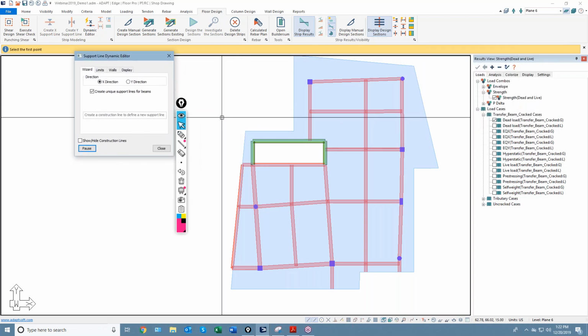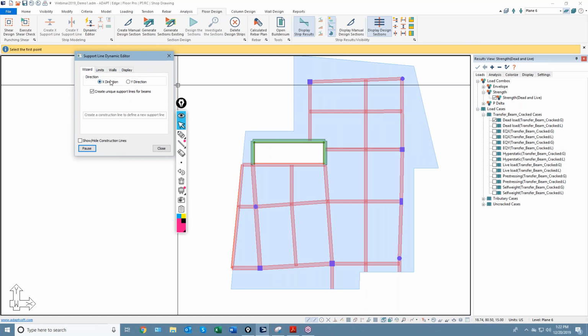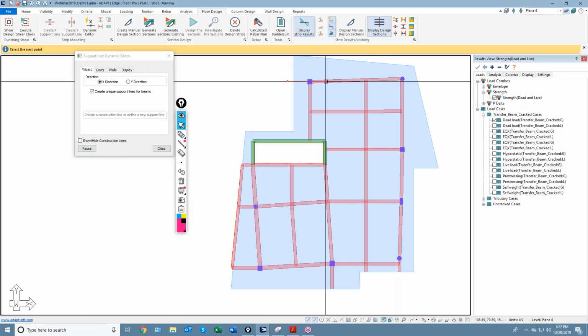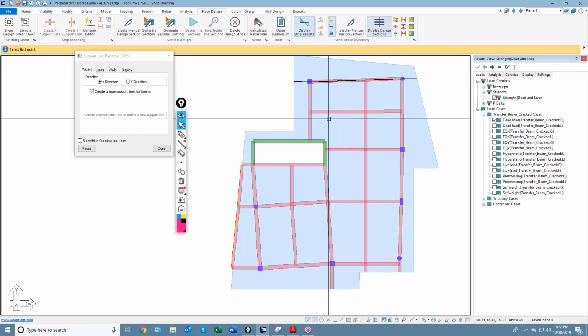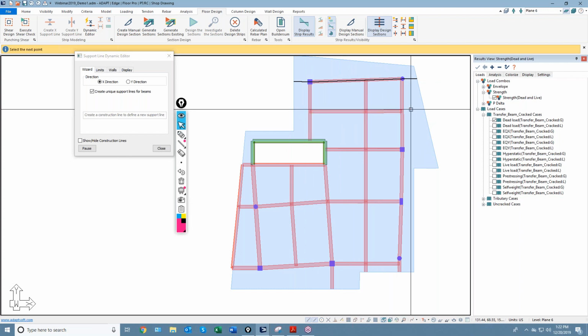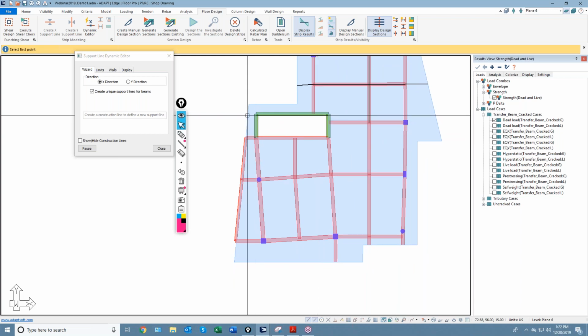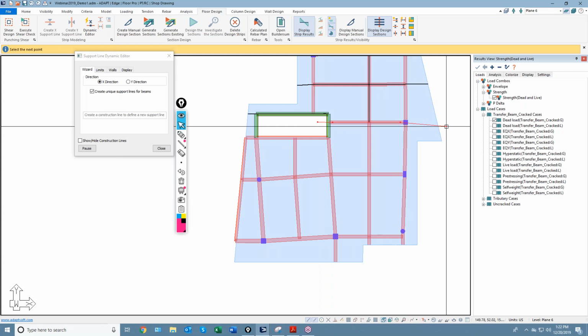We just have to be a little more careful on a level like this, where when I'm snapping, this is a continuous beam, so I can snap near point 1 and 2 of this beam. This beam is broken up into 2, so if I want the program to automatically break this up, I have to snap on the interior points like so. And then I might do a wall location. I'll just do another beam location and so on.